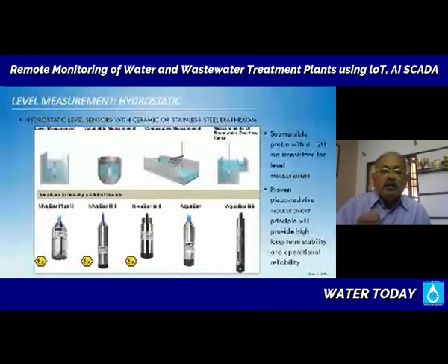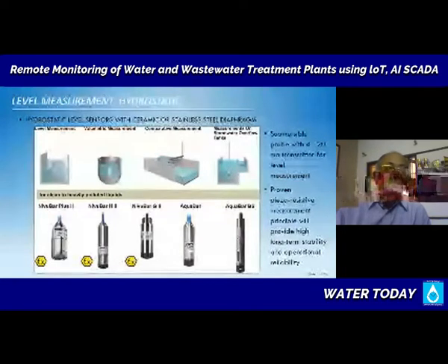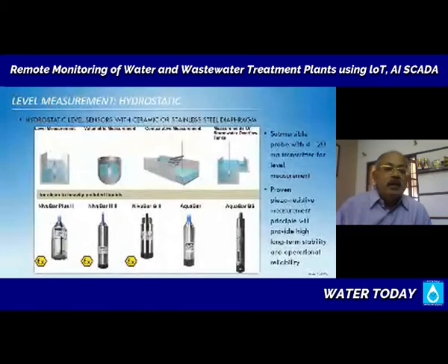And what you have is a sensor which is made of ceramic or a capacitance type sensor or some such. The sensor is hanging from its own cable into the process area where you are measuring. Now, comparative measurement, that's one thing that I would like to point out to you. What you are seeing there is relevant to water systems where you are having screens. Screens are mechanical devices that stop suspended solids from going into a treatment plant.